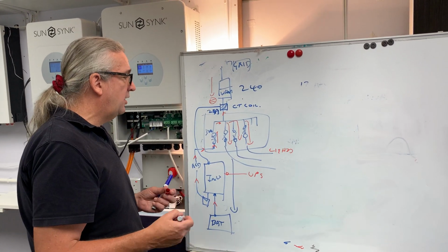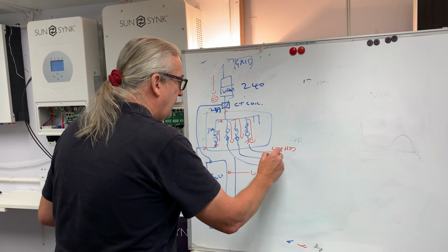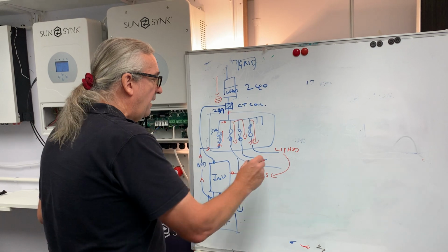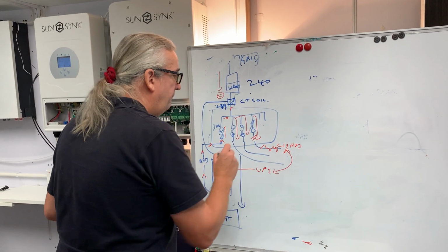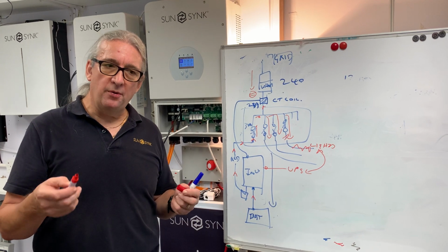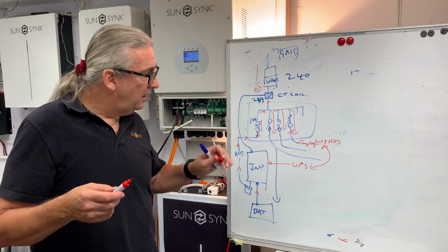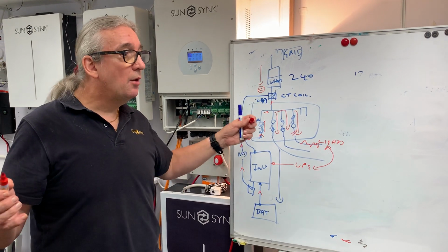If you're in a risky area, you might call it essential load. We remove it from here and connect it into here, and we don't need this wire here. That means even in a power outage, our lights will operate. So our lights will always operate 24/7. If there's a power failure, the lights will carry on, and maybe our alarm system or whatever.